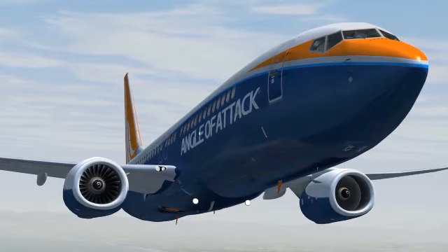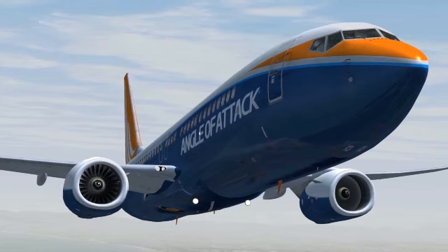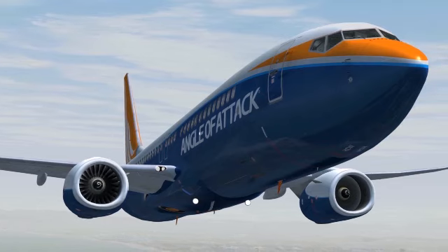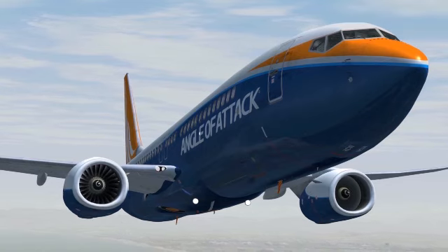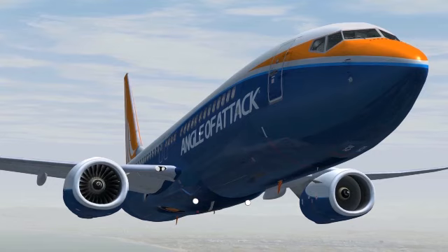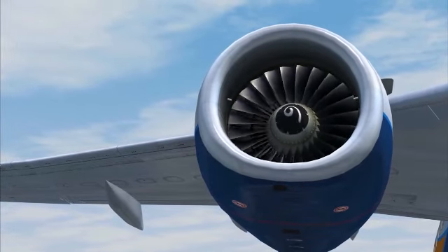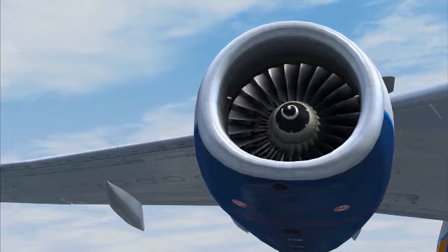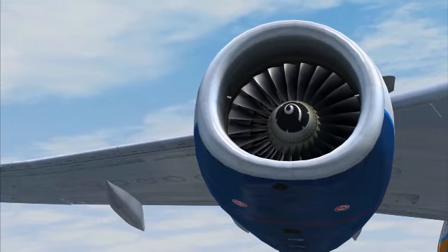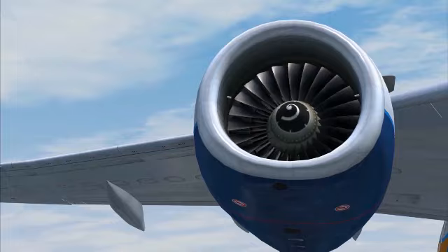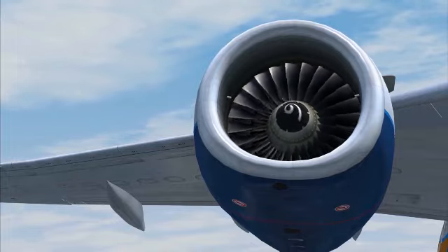In a windmill start, the N1 fan behaves like a windmill and spins as the aircraft moves through the air. The 24 fan blades on the 737NG are very aerodynamic. This method does not use bleed pneumatic power, therefore it doesn't use the engine starter. Instead, it takes advantage of the air that is rushed into the windmilling engine to turn the compressors and get the engine restarted. In this case, the engine start switches must be placed in the flight position, where both spark igniters operate continuously.